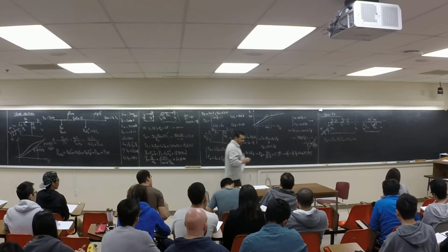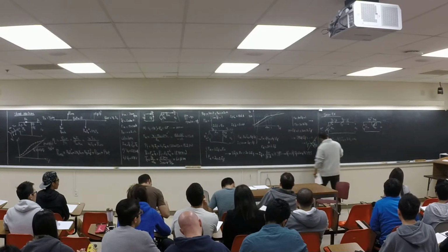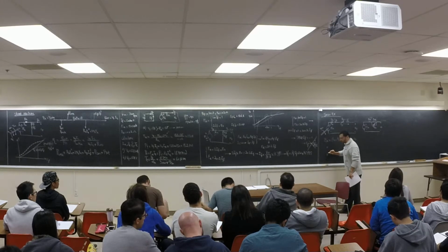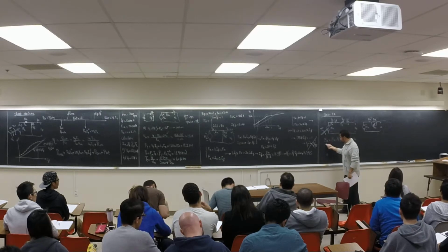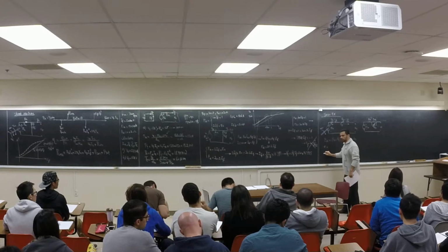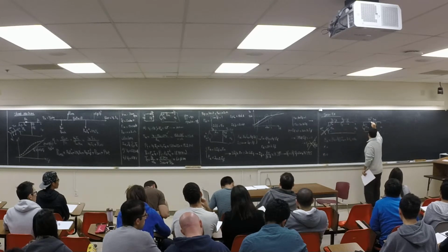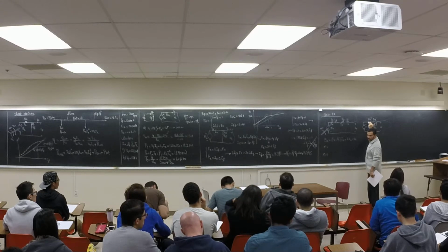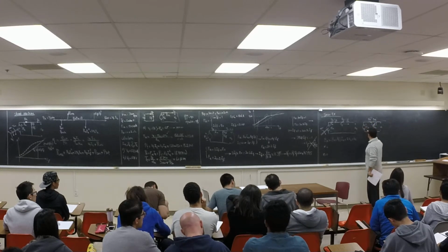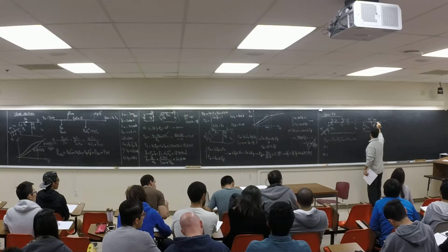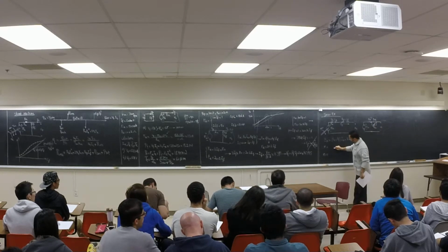For example, this machine, usually in the lab, it tells you there is an armature connector, for example, giving you A1 and A2. Basically, it's giving you these 2 points. Because RA is also part of the armature, right? And it gives you, for example, F1 and F2.